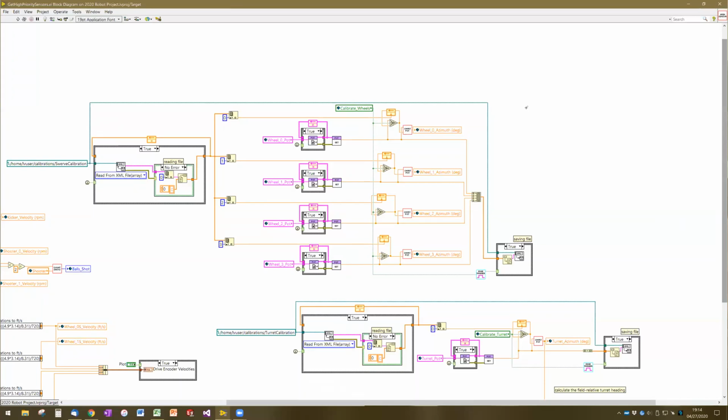Alex? We need an IMU and 4 wheel encoders. Okay. We probably don't need the wheel encoders specifically for field-oriented control, we need them for other things. But yes, we do need an IMU to do field-oriented control.